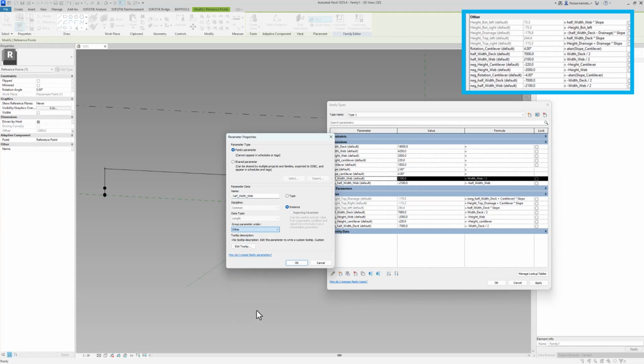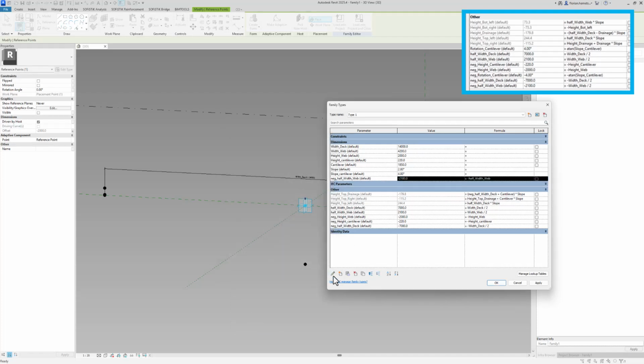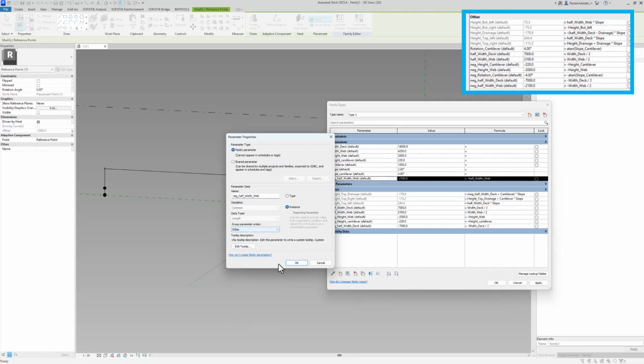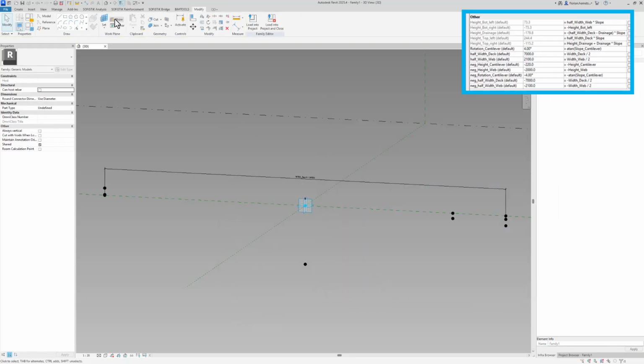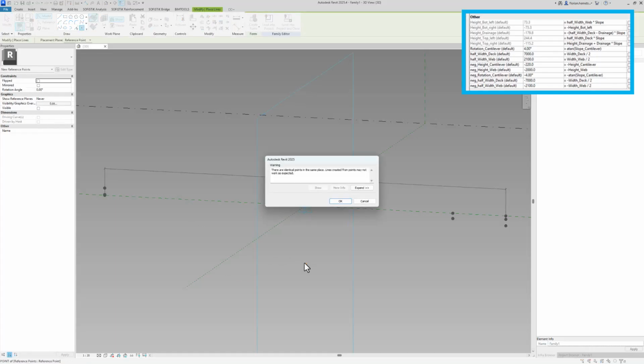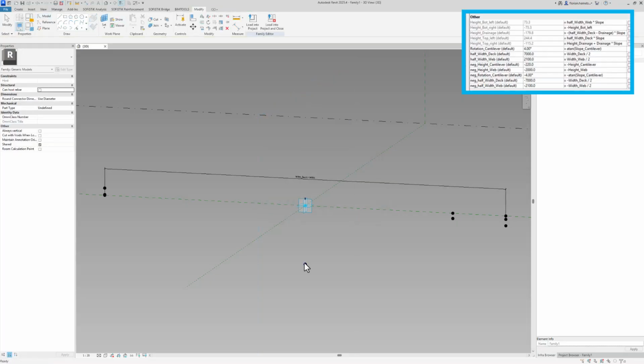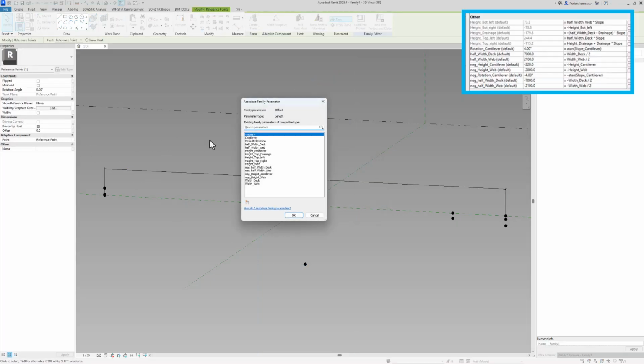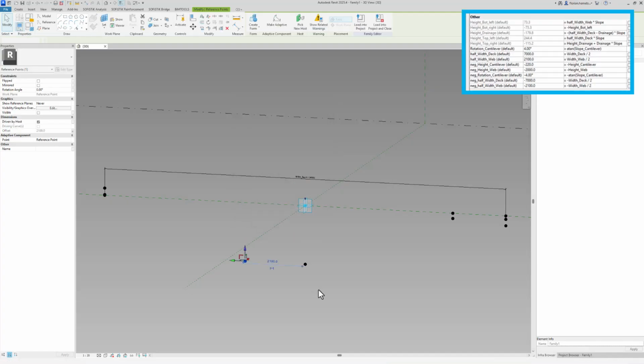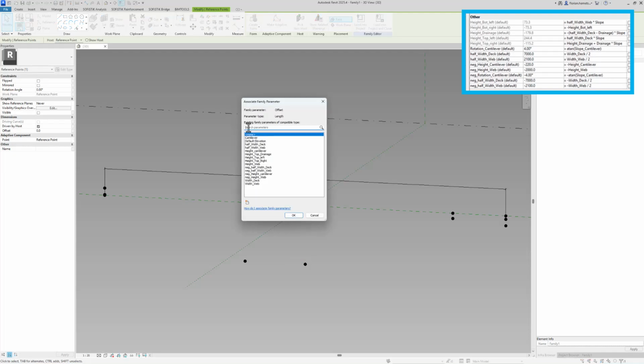Change it to other, simply for it to be cleaner. I now go to this reference point, assign the horizontal offset for 2 points that I can create in here. On the one hand, I want to assign half width web as well as negative half width web.